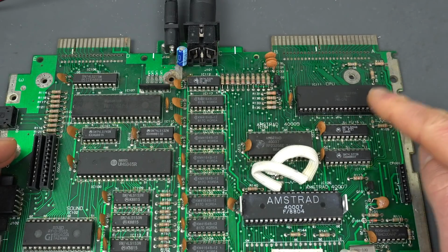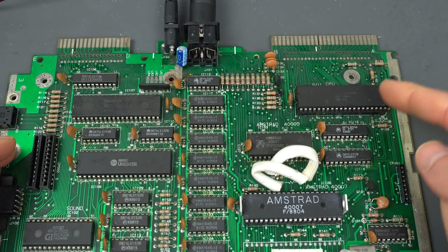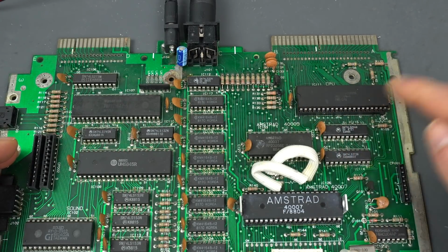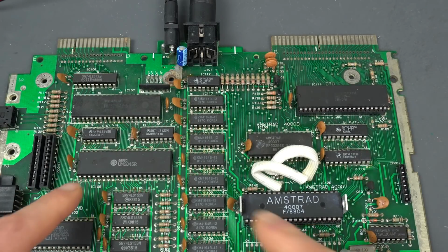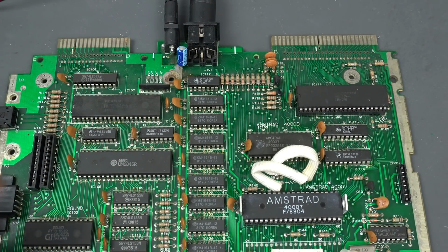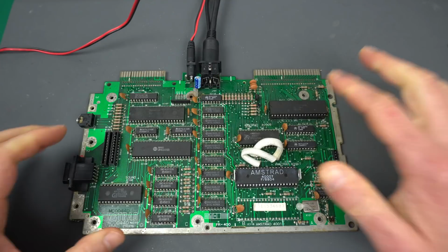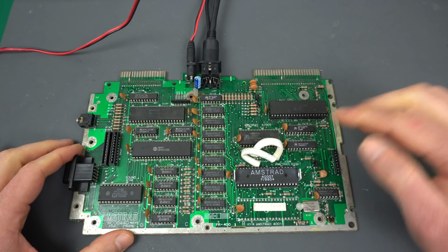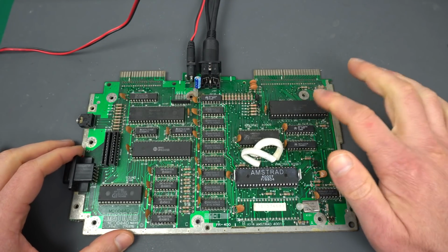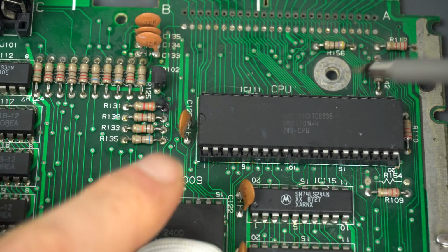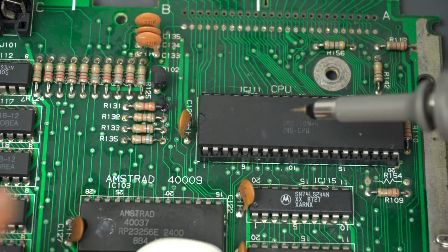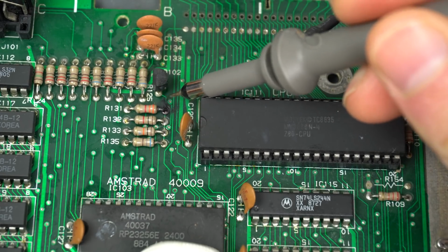But I suppose it could be partially working, and the gate array is able to display some things, but some other functionality in the Z80 is not working and is not able to initialize the CRT controller correctly. So it's worth, at this point, examining some of the signals on the Z80 and make sure that everything looks okay. And as I was getting ready to check the Z80, look what I found in here.